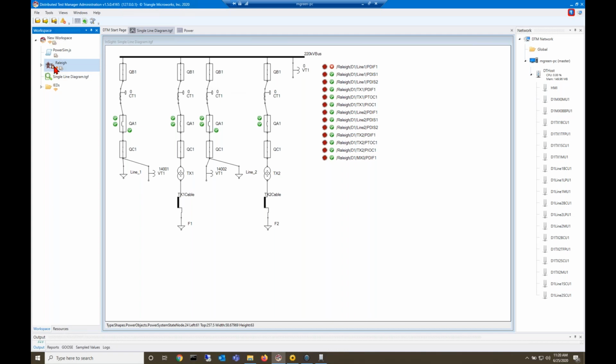Now, like I mentioned earlier, we have that library of logical nodes and equipment scripts. And essentially what we're doing is we're setting up the values that they're monitoring based on these inputs and outputs. So in order for the recloser to know when to initiate its functionality, we need to tie that to the trip signal. But the scripts are all going on behind the scenes.